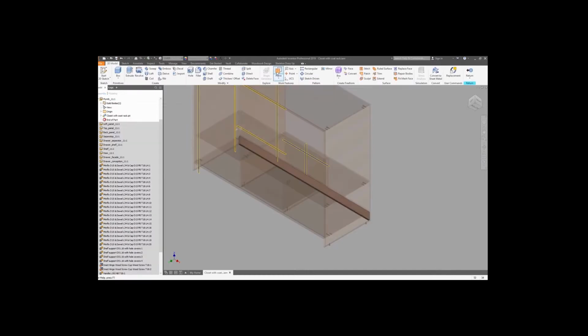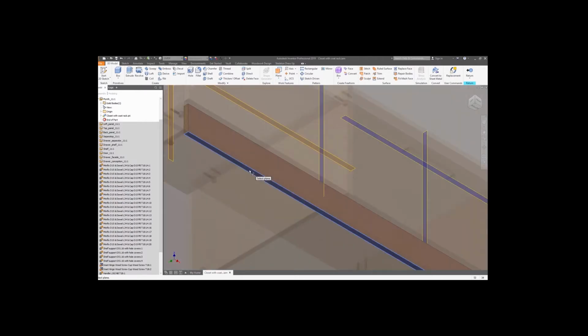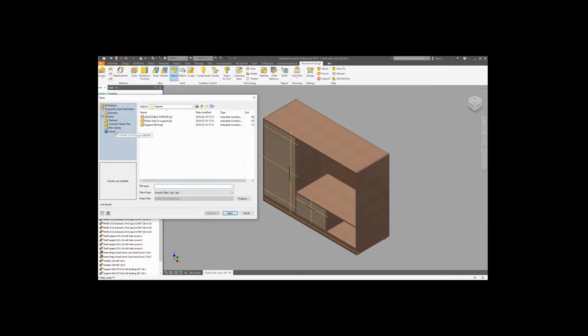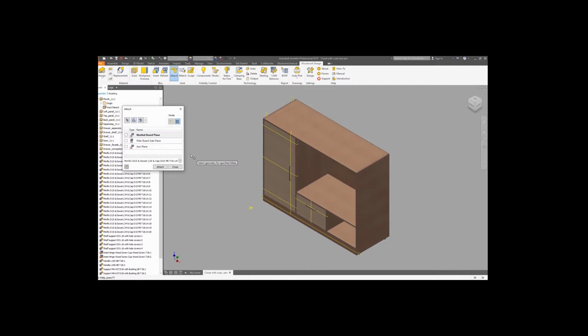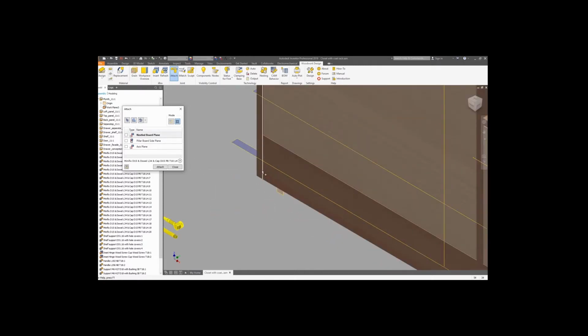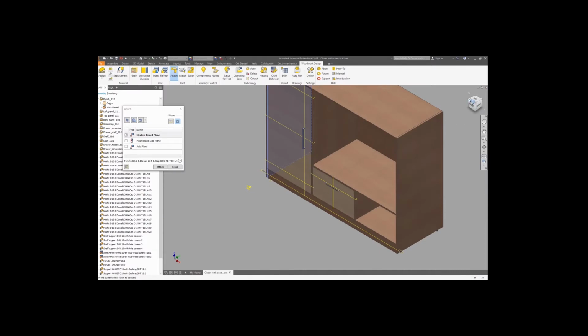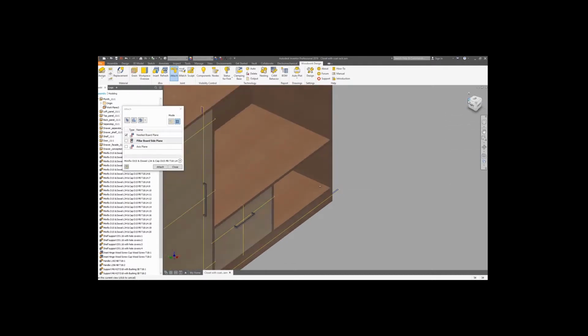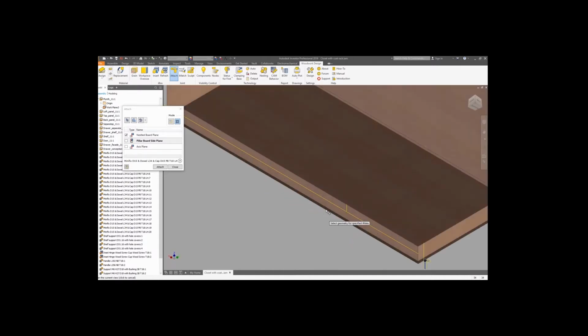Now it's time to fix the plinth in place. Again, the work plane in the middle. Go back to the assembly level. Browse through the structure of the library. Pick fixed join, minifix. Choose a configuration, and that's it. So now we need to just pick the appropriate geometry items, as we already did in the previous steps. There are the nested boards on the left, on the right, and since we want to hide the joint, we will pick the invisible side, and finally the axis. So the joint is in place.